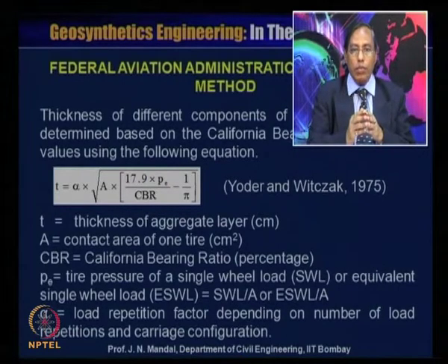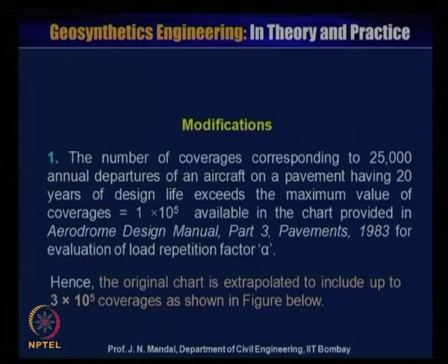ESWL, that is equal to SWL, the single wheel load, divided by contact area of one tire, or equivalent single wheel load divided by A, that is contact area. And alpha is the load repetition factor depending on the number of load repetitions and carriage configuration. So, some modification has been made.